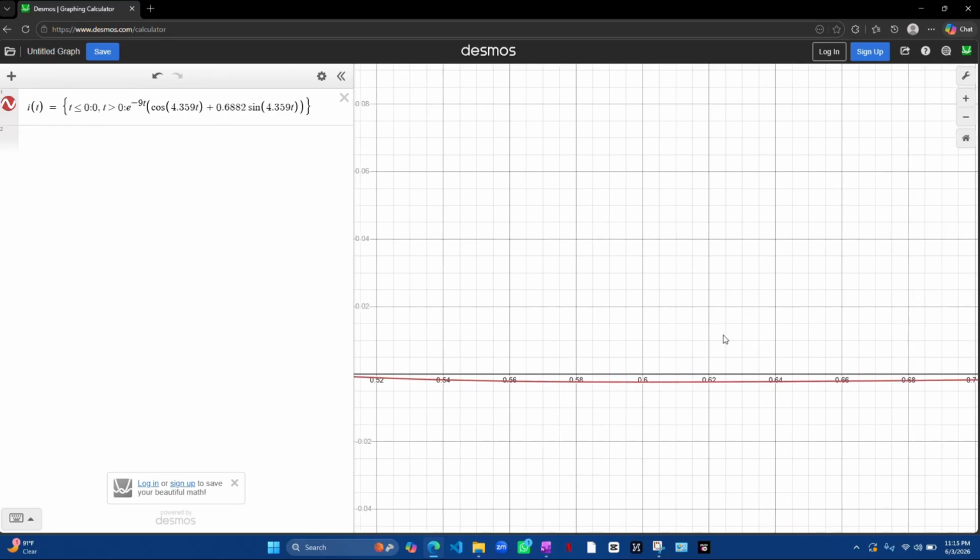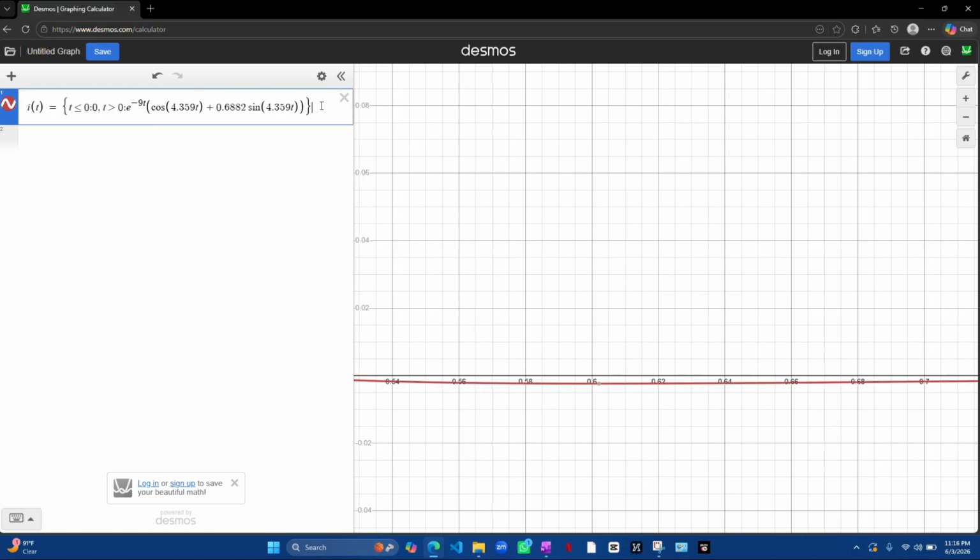Maybe I can move it to the right a little bit. So we can see it starts to swing, and we get minus 0.0023, which is essentially minus 2.3 milliamps. So that's accurate. The only caveat is that the time we get is 0.602, where we got 0.609, which again is a very small difference, so that could be neglected. So this point makes sense.